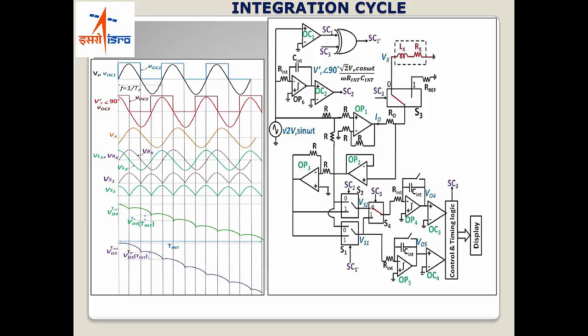So you have a square wave of that. Then you can see that this portion is an integrator. When you integrate a sine, you get a cos wave, and you get a zero crossing signal for that also. So this blue square wave and the red square wave are the outputs which I am going to use to control my particular switches.